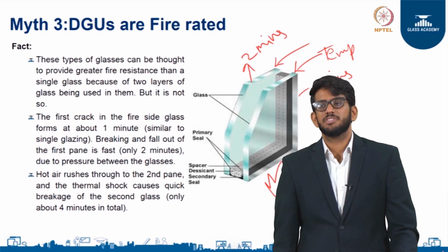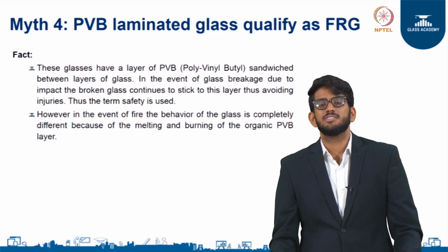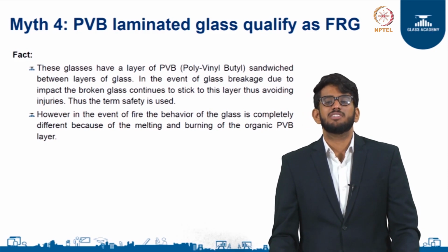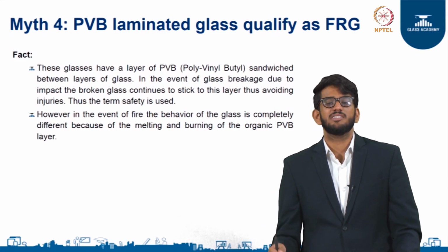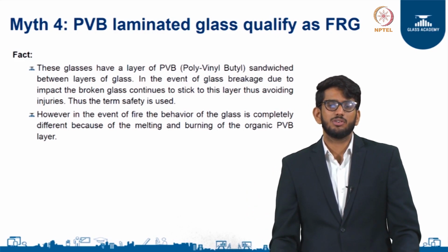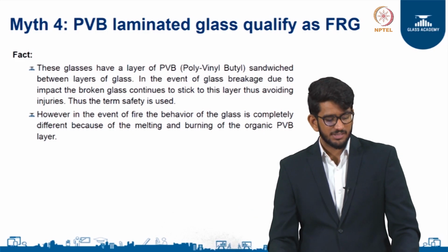The next misconception that I am going to take you through is the use of PVB laminated glass, which people believe qualifies as a fire resistant glass, because at the end of the day it is a laminated glass and it is referred to as safety glass in the markets.